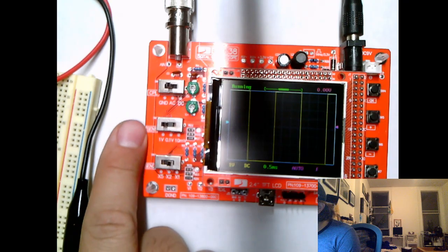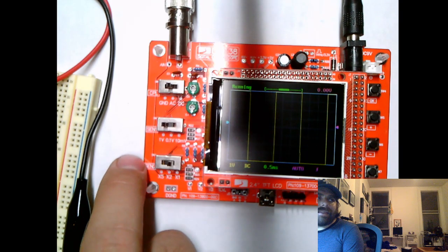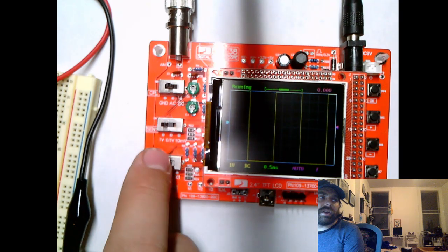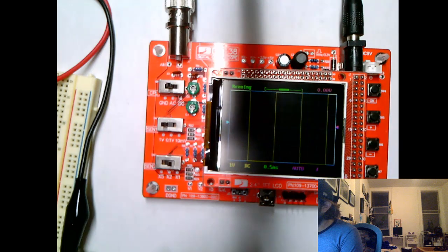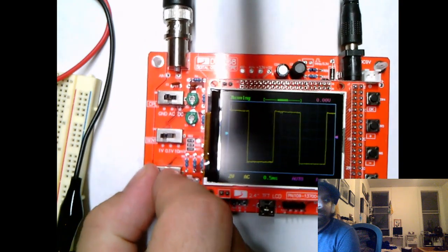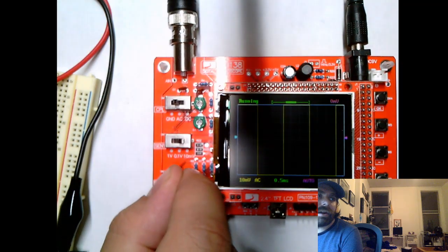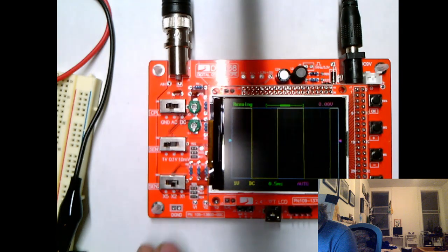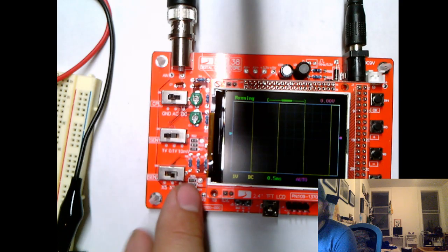And then I'm going to go here to my sensitivity 1. So I have 2 sensitivity switches here, and these are kind of like your coarse and your fine adjustment for volts. Right now, I'm at 1 volt per division. And this is pretty loud, right? I think the output of this is pretty big. So even if I switch this, I have to use my coarse adjustment. If I move this down, it's going to get bigger and bigger. So I'm going to keep this at 1 volt per division, which is all the way at the left. I can also set this to 0.1 volts per division or 10 millivolts.